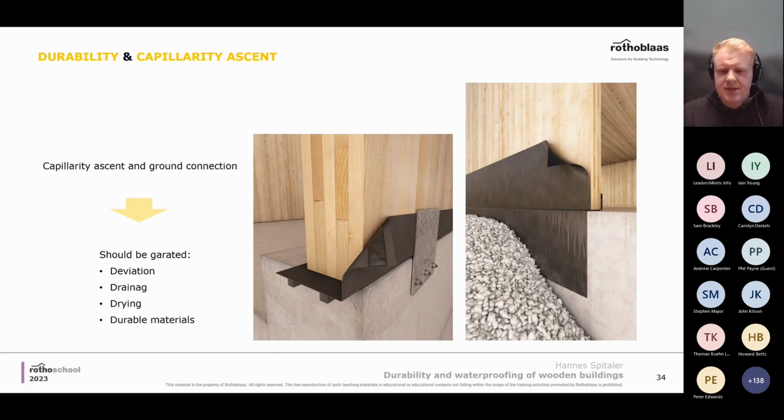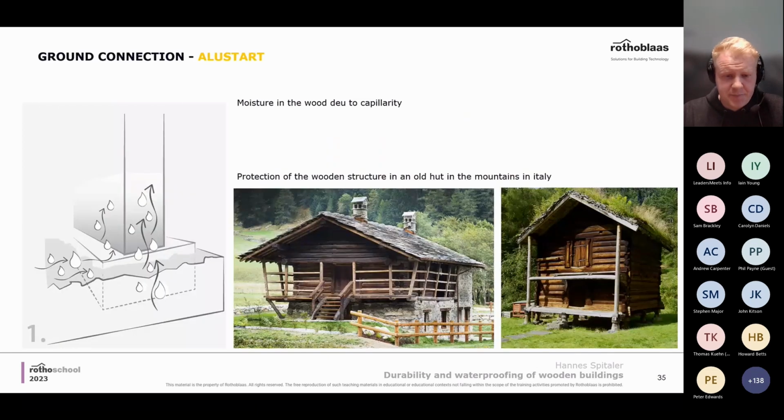There are different ways you can do this, so you don't necessarily have a direct application, with your wall structure directly on top of the foundation, but something in between. Maybe it's made of timber, maybe some other element. But generally, you're always trying to stop the humid foundation or ground from going into your wall.